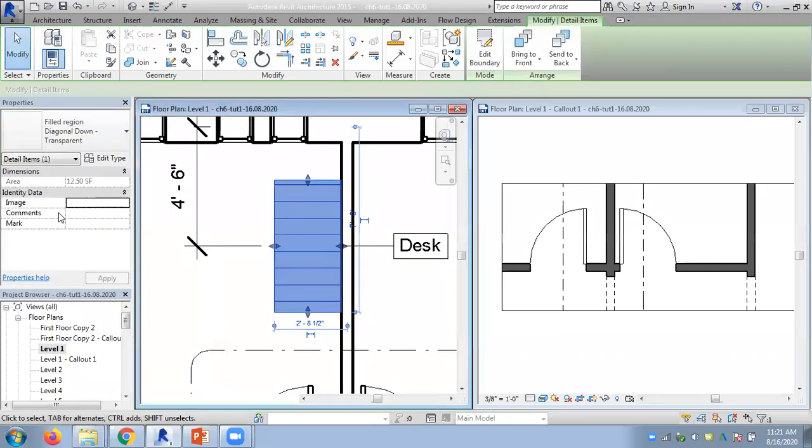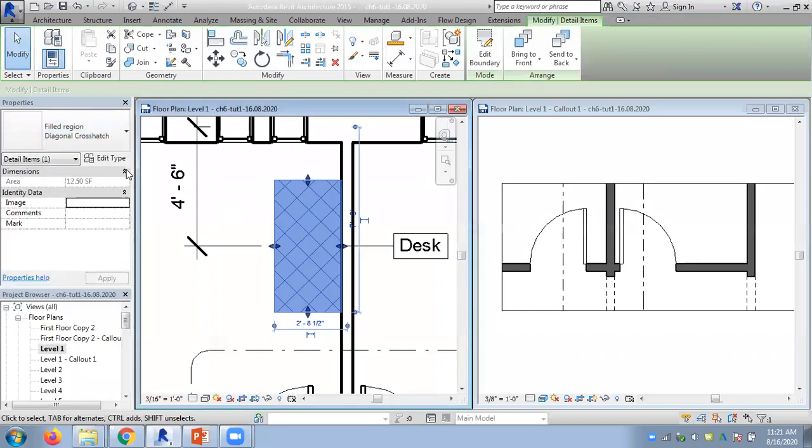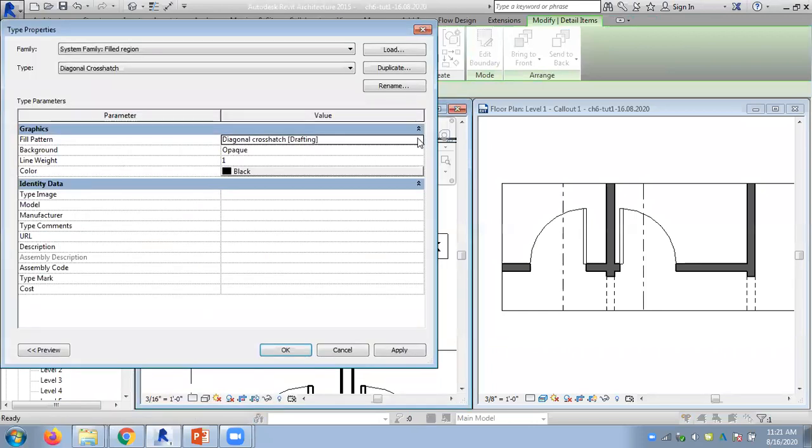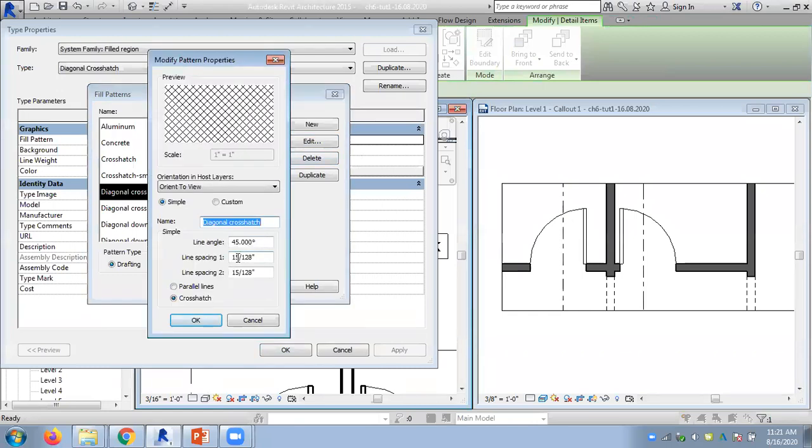So how can I change the hatch scales? I'll show you later. Now we can come here and go to this editing, and there's a tool here to change the hatch angles and hatch spacing. So if I want a small space, just put it like this.